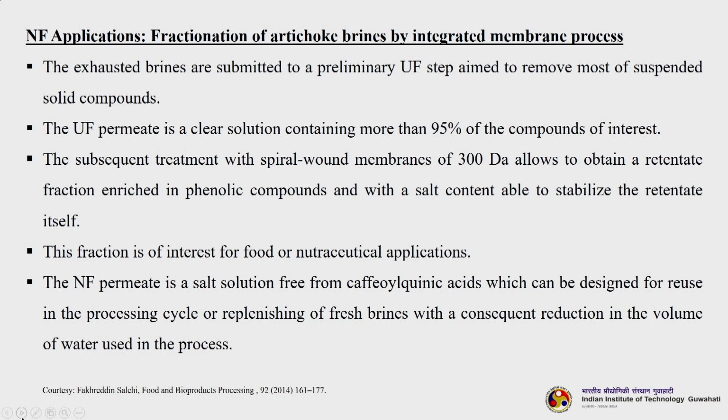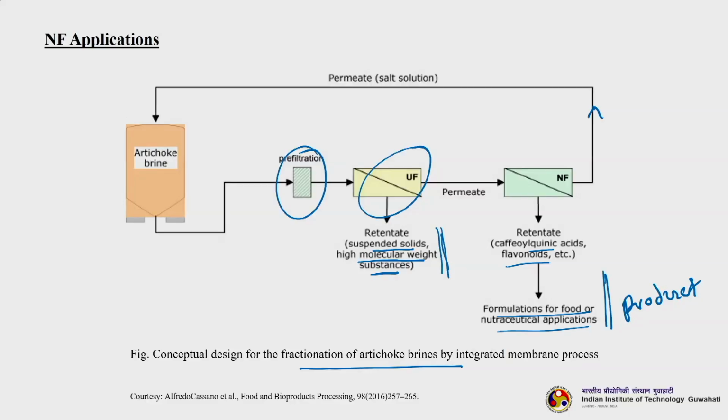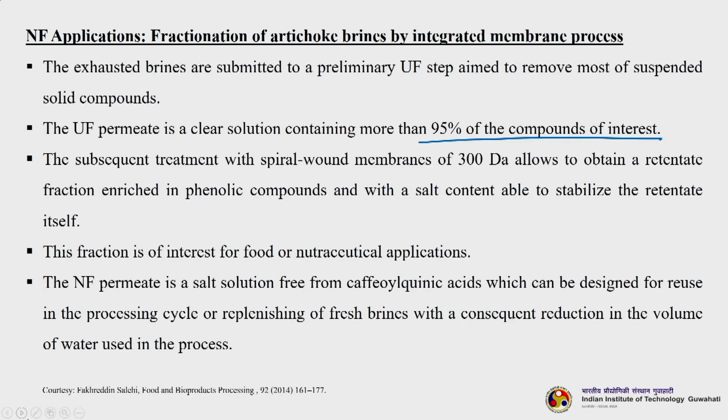This is what I already told you. So, the ultrafiltration permeate is a clear solution containing more than 90% of the compounds of interest. So, it takes out all the larger molecular weight components, as well as your TDS, most of the suspended solids. So, components which are smaller molecular components, these caffeoylquinic acids, flavonoids, etc. So, they will be fed to the nanofiltration system.